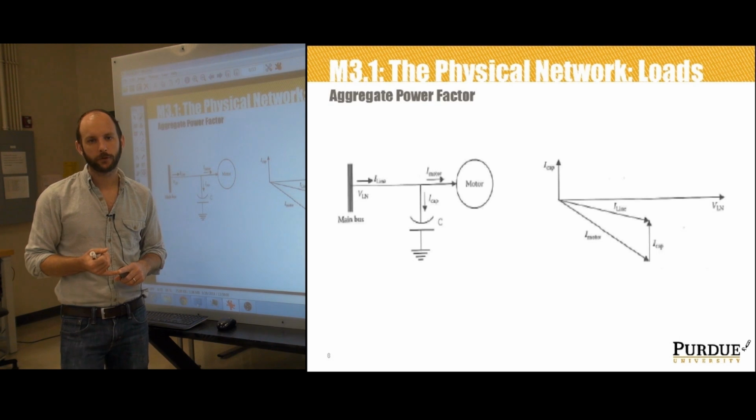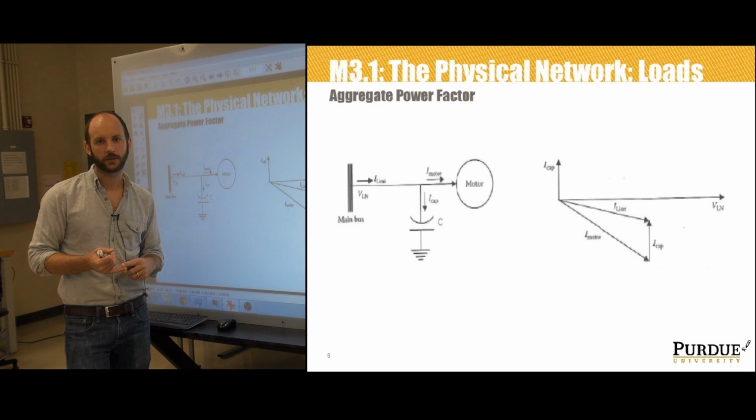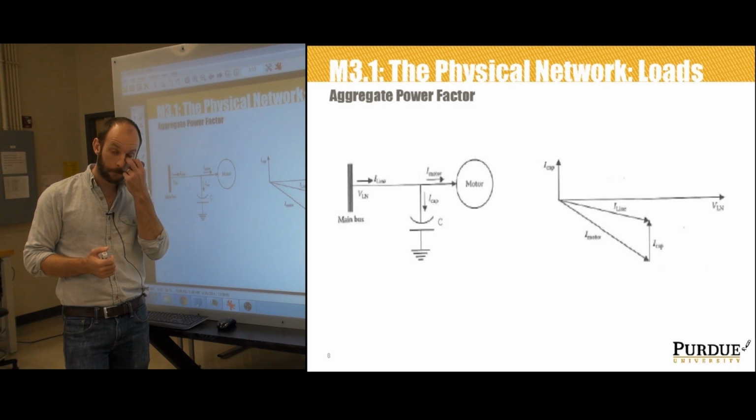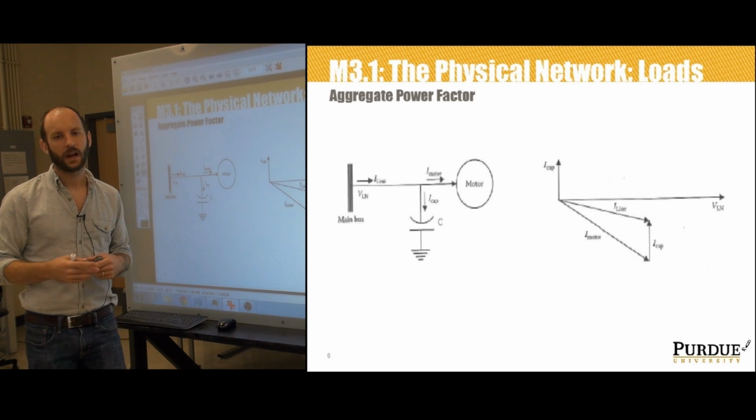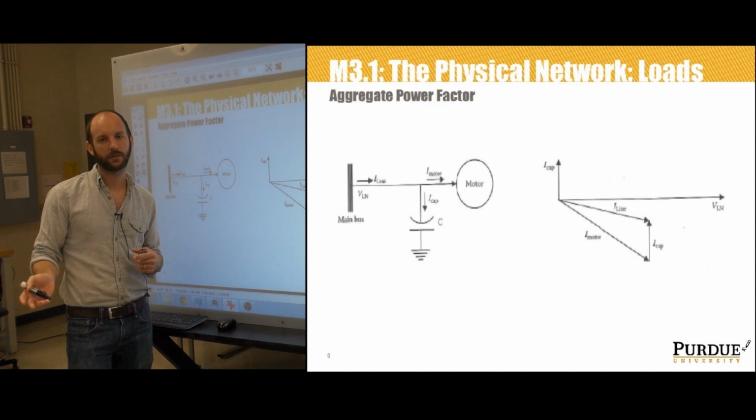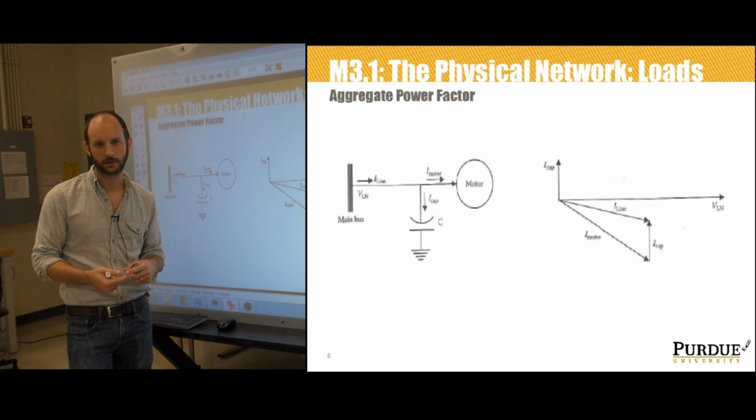When we're considering improvements that could be made to the power factor of a system, the first thing that we want to notice is that most loads that are actually out there look to be partially inductive rather than capacitive. And therefore, poor power factors lower than 0.9 are typically caused by large inductances in the load circuits, and not by capacitances.